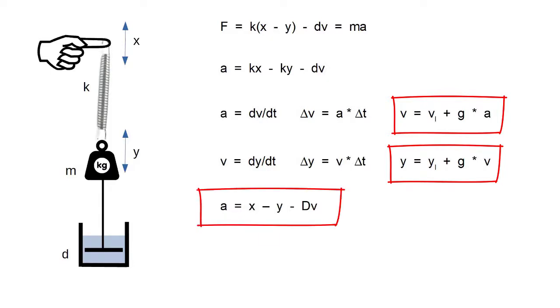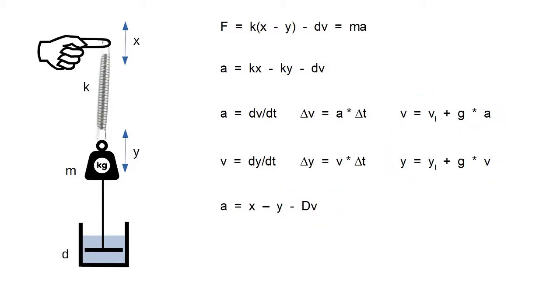Okay, so now let's test it out. But before we do so, a couple of things to note. The cutoff frequency of the filter, as we said, is proportional to the gain, and it's given by the gain times the sample rate over 2 pi.